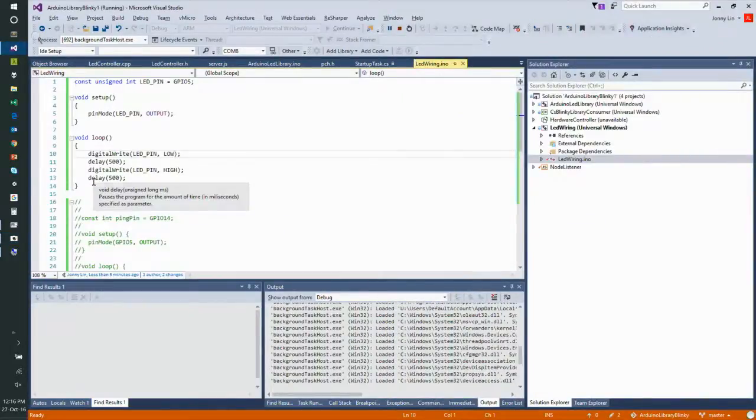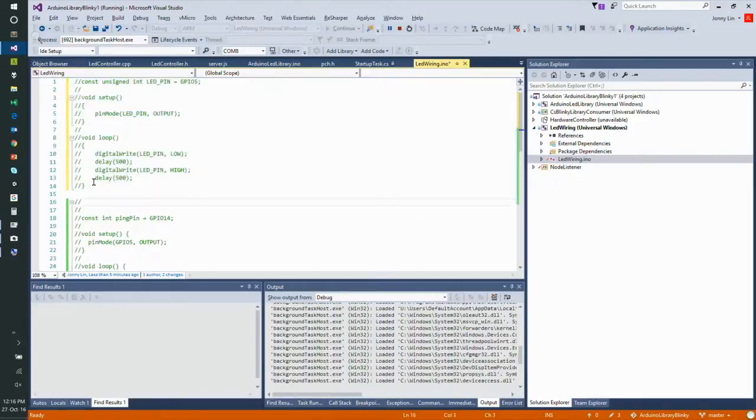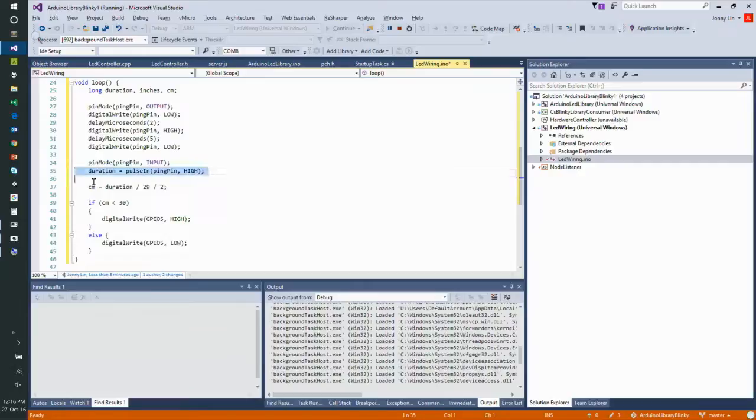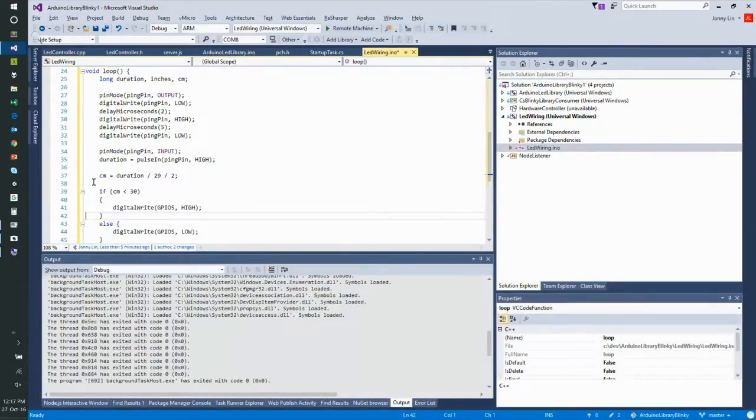which is the sonar that we were talking about. And so this one's slightly more complicated. Again, you see the 2 microsecond and then 5 microsecond handshake, and I calculated the duration. Exactly the same functions, I just made it a little bit simpler. And because I don't have serial on this machine to visualize it really well, what I'm gonna do is get it to turn the LED light on when it's too low, when it's too close.